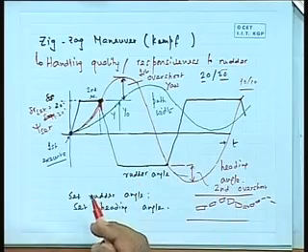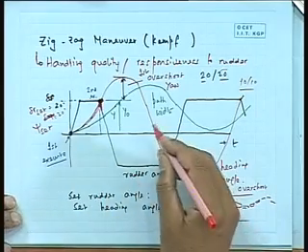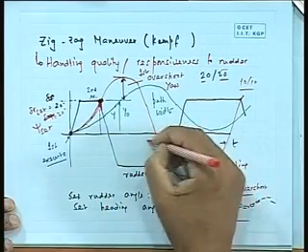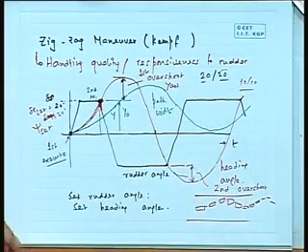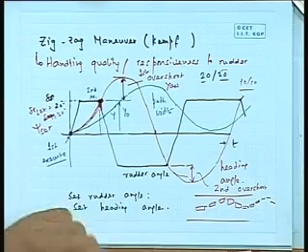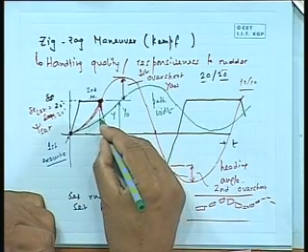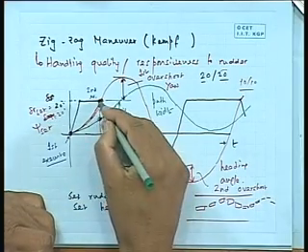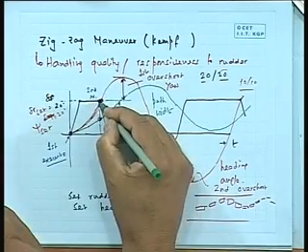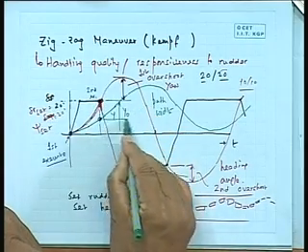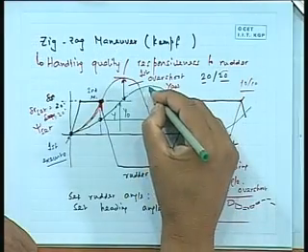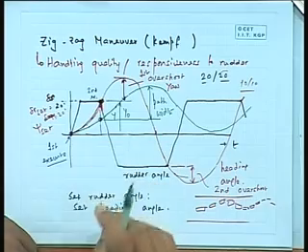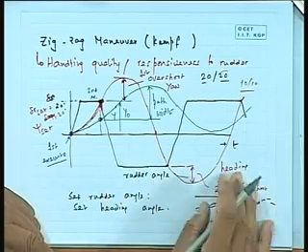Then comes the question of time. I can also call this yaw overshoot. Now yaw, same thing. My yaw was at this point when I have my execute. At this point I change the rudder. So my ship would have started to come back on the other side, but it did not. It started going in the same direction for some more time. So this becomes my overshoot path width.